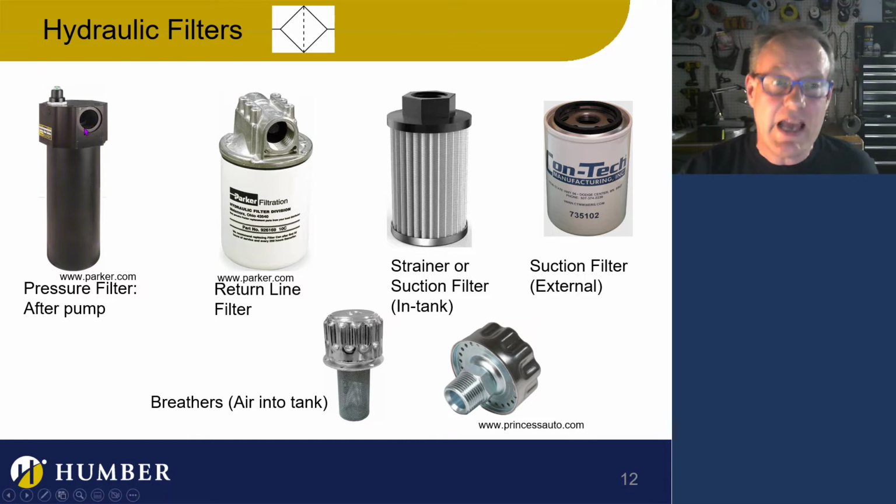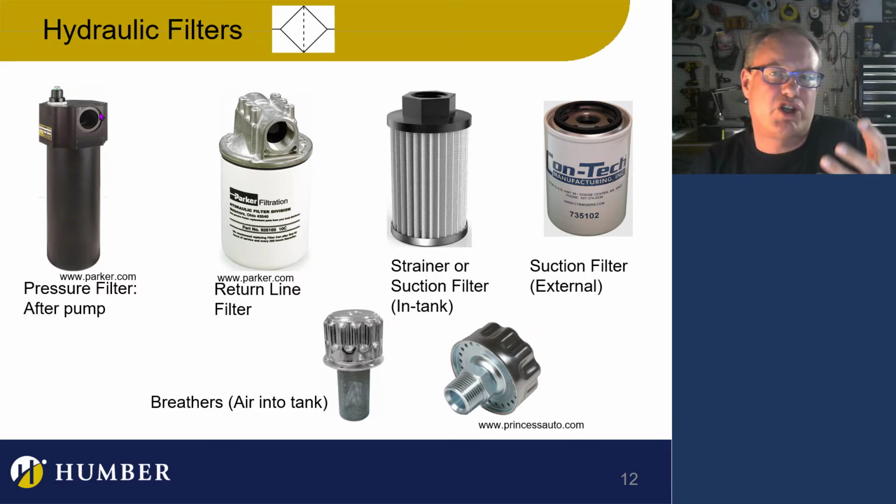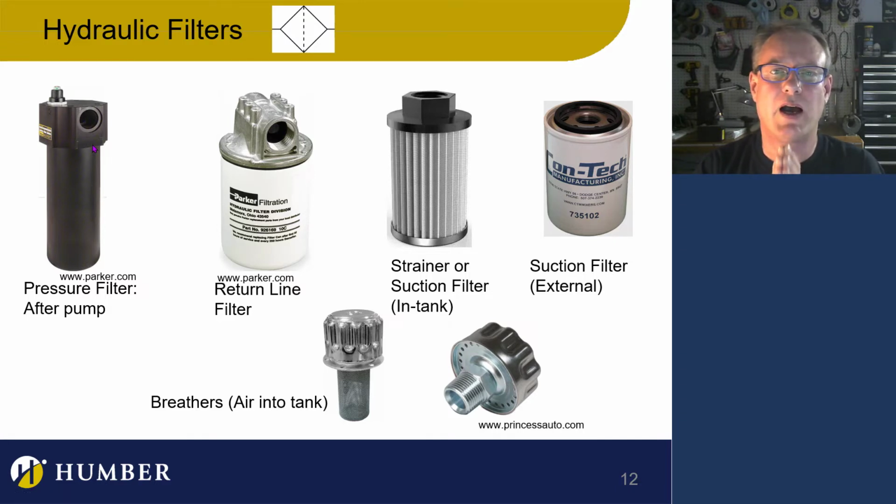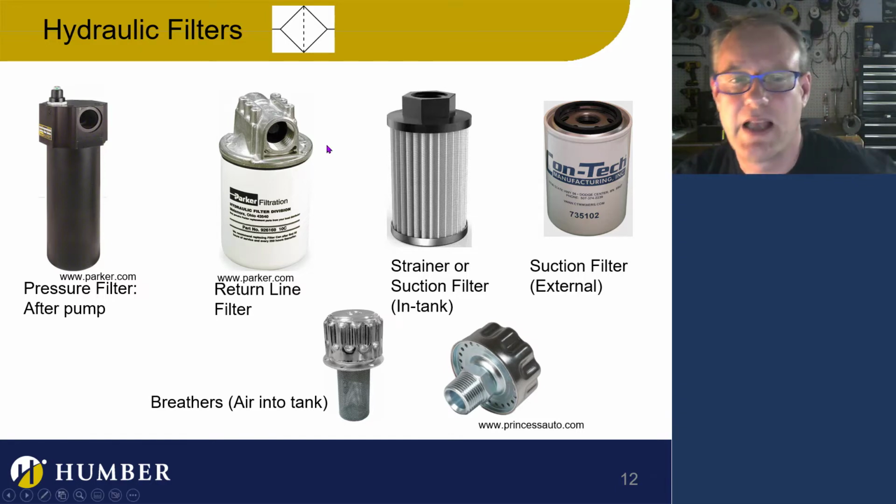But an inline filter is going to be after the pump, and the fluid going through is going to be under pressure. It's going to be really pushed through. So you can actually put a very fine strainer in here and collect a lot of the dirt. But ultimately, the best place to get the contaminants out of your fluid is in the tank, right? The best place to do it is in the tank, and we'll talk about that when we talk about kidney filters. Anyway, there you go.